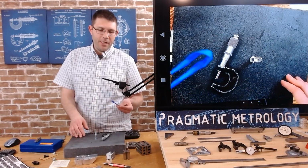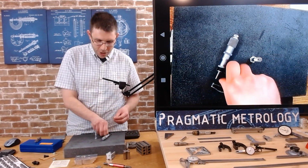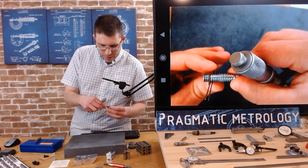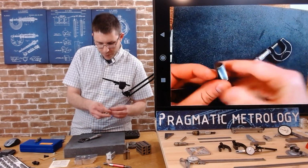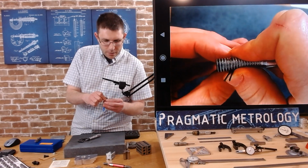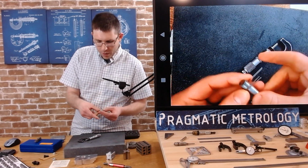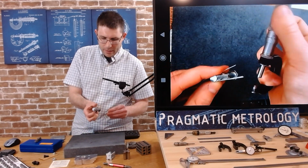A machinist friend of mine showed me this trick where if you tape the wires together, it can make it a little bit easier, a little bit cleaner. So we're going to try to do this. What you need to do is get 2 wires on and then a single wire across it in the middle of the other 2, as close as you can, so that way the micrometer is resting evenly across them. So you're going to do 2 on one side and 1 on the other.